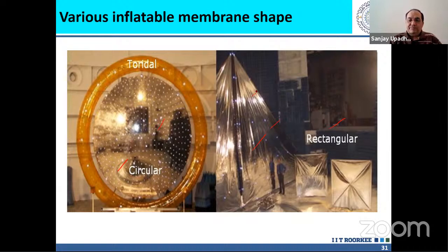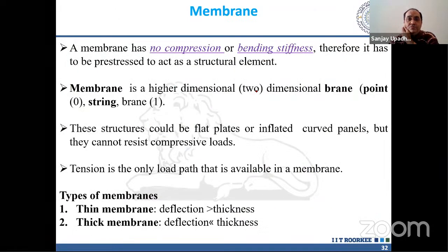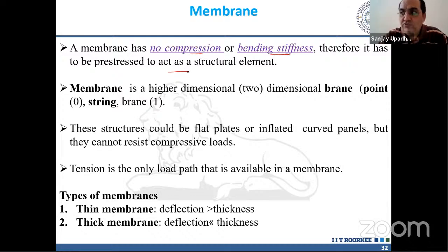We need to study this. These are the various shapes of inflatable membranes. And what is a membrane? A membrane has no compression or bending stiffness. Therefore, it has to be pre-stressed to act as a structural element. When you develop some FEM code, or work in ANSYS or Abaqus, and make a model, the membrane is a structural element. A membrane is a two-dimensional structure.